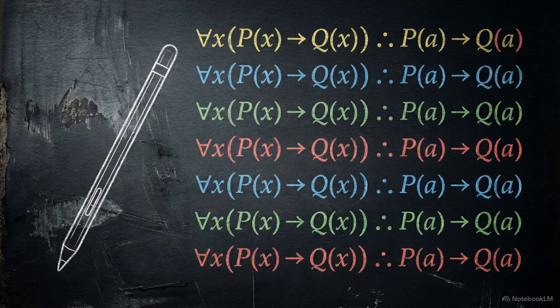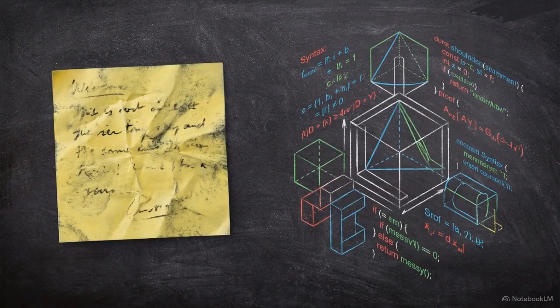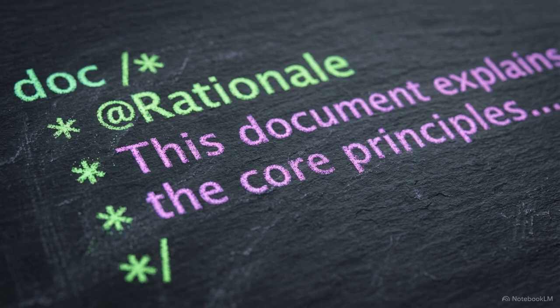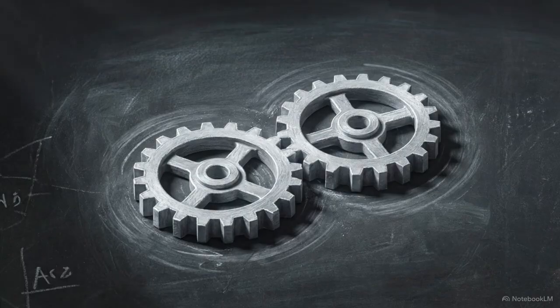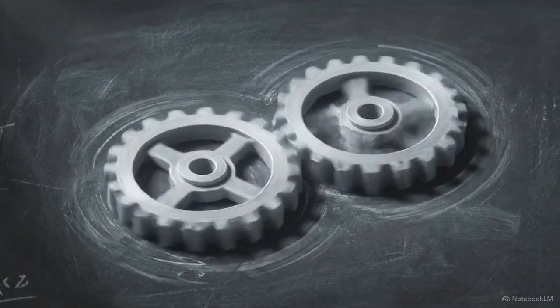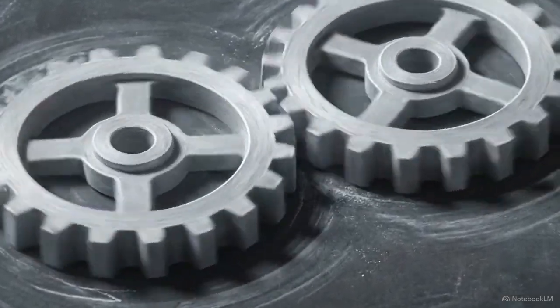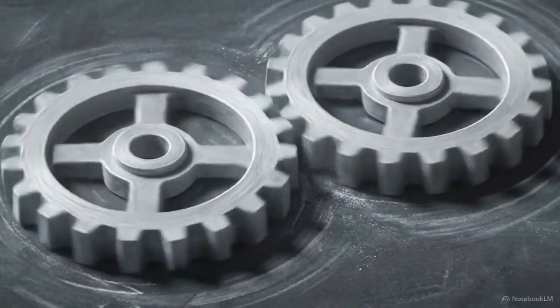Capturing the rationale behind these design decisions is the next step in the process. SysML v2 replaces disjointed graphical rationale notes with direct textual integration. Engineers use inline doc blocks and structured rationale metadata tags, placing them next to the relevant verification code. Verification and system rationale are now active, fully executable logic, residing perfectly synchronized with the core design data.